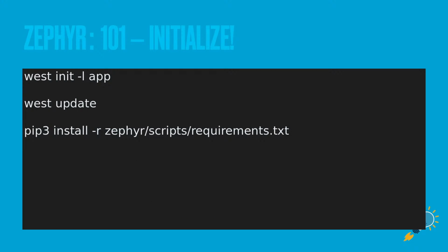So that is the basis for at least getting started. You can initialize and get all your dependencies. So just with the West YAML, you can start initializing actually using things. So the west init -l, so -l is for local, and then you want to indicate the folder where the West manifest is located.